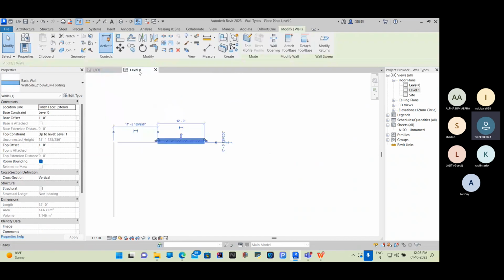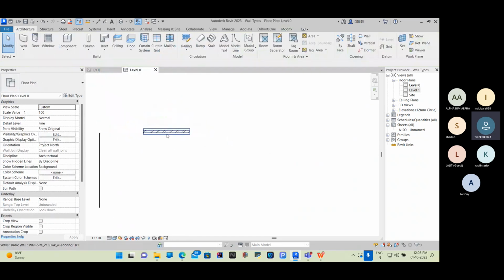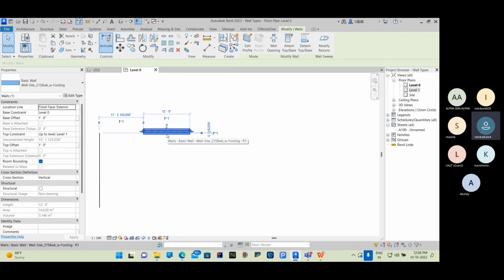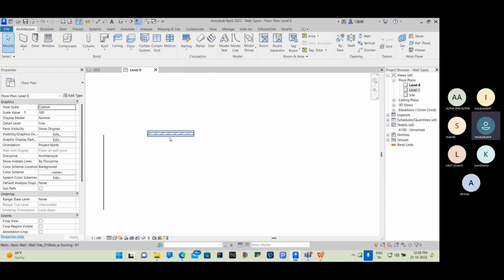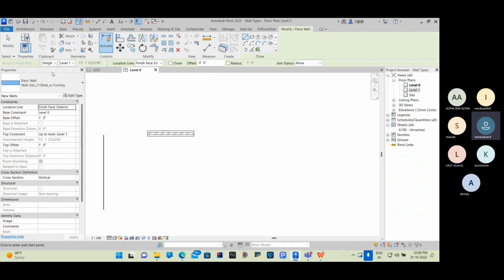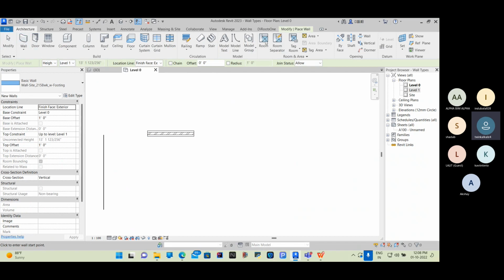And if I go in the floor plan again, I select the wall, and whenever I want to create a similar element in Revit, similar object or element, sorry, I just type CS on my keyboard, create similar. So I just did that shortcut. Or if you want to create a new wall, fresh wall, I'll just type WA. WA is a shortcut for wall. If you just hover over the icons, you can see the shortcut keys also.